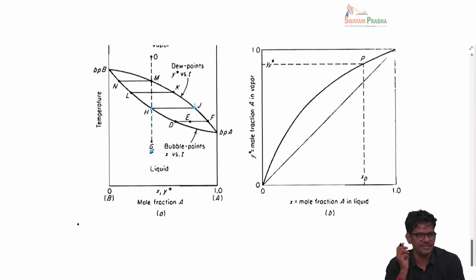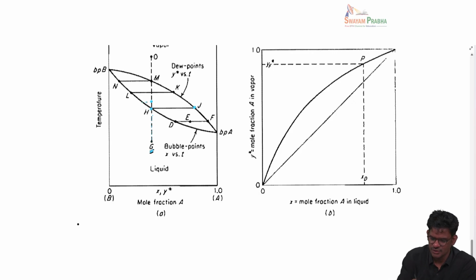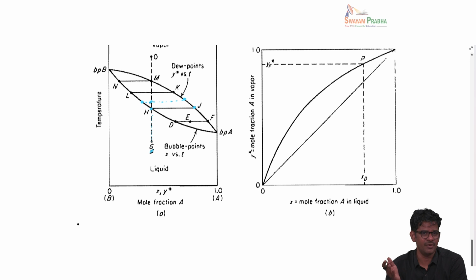Okay, now let's say you have closed this vessel and you continue to heat this further. When you heat this further, you may go here somewhere. Okay, but that is within the two-phase region. It's going to phase separate into vapor and liquid, and the liquid will have a composition corresponding to here, and the vapor corresponding to the composition here. Between this point and this point, the average composition remains the same because you've closed the vessel, the total mass has to be inside the vessel. So the average composition remains the same. However, it has become more like a two-phase system now. One that is liquid phase corresponding to this composition, and this corresponding to the vapor phase.